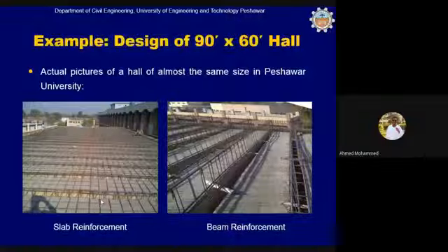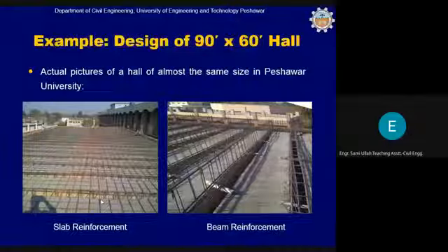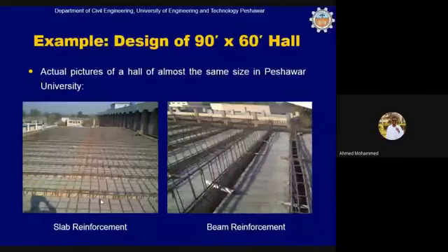Although I couldn't understand your question, I will try to explain that when the slab reinforcement is going into the beam reinforcement, and the beam reinforcement in the form of stirrups, because the stirrups are common now in this part, the stirrups will be cast within the slab concrete.